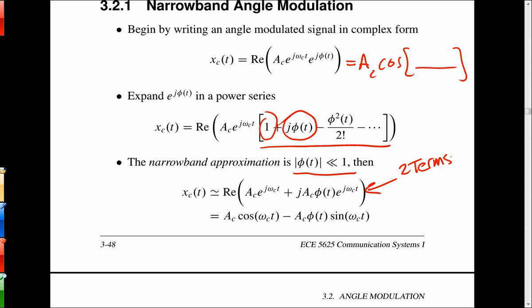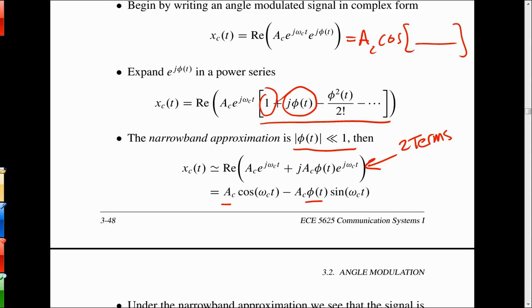So this looks almost like amplitude modulation. In amplitude modulation, you had a pure carrier and then you had the message going up. The only difference here is that now you've got things in quadrature, sine and cosine quadrature is what I mean. So the carrier is on cosine, the pure carrier is cosine, and the sidebands are put on a sine type carrier.